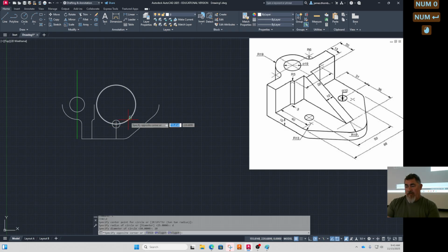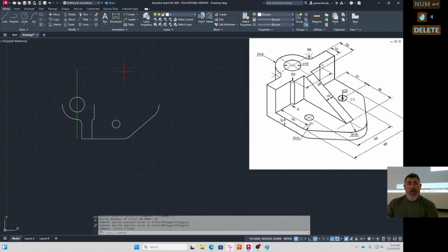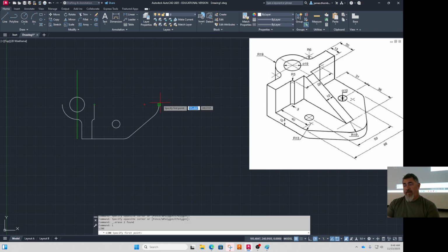And so that's one of the things, just play with it when you're doing commands. So, draw a line, and just touch the ends. Those two are just going to do that. No, I didn't click. I just moved the mouse over it. So just move the mouse over it, and it turns on. Move the mouse over it, and it turns off.